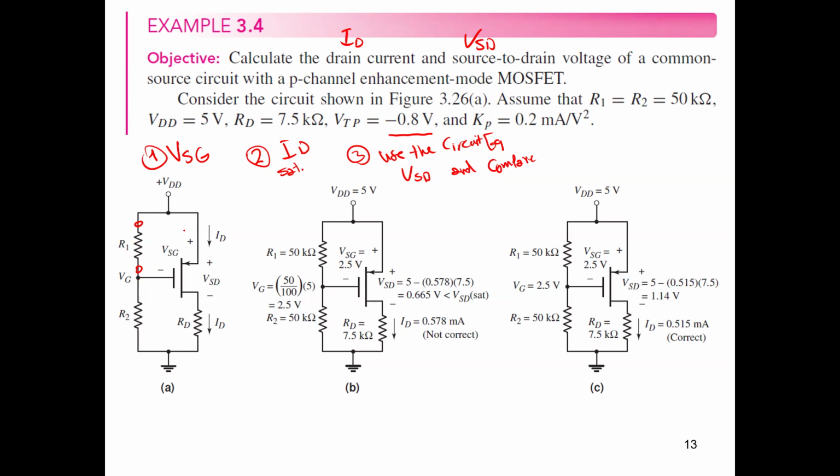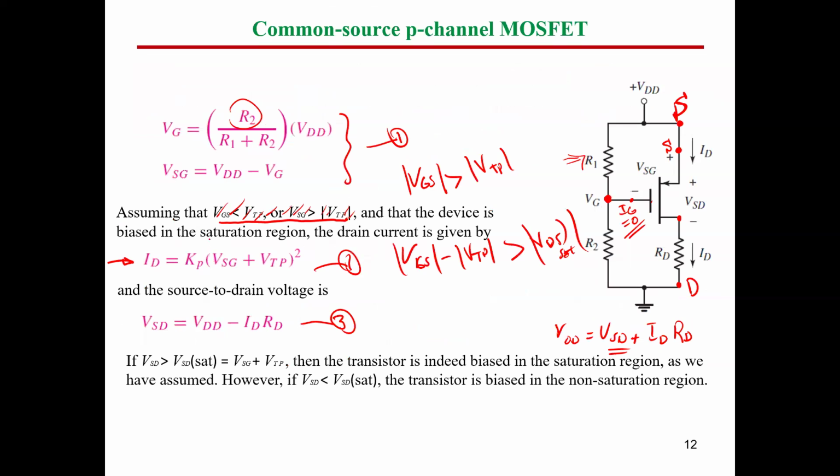So for sure, you can say R1 divide R1 plus R2 times VDD will provide you with the value of the volt across this resistance. You can call it directly, this is VSG. I will write it here in the notes if you would like to make it in one step. So I can say here, guys, VSG equals R1 divide R1 plus R2 times VDD.